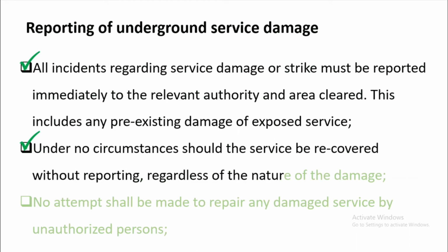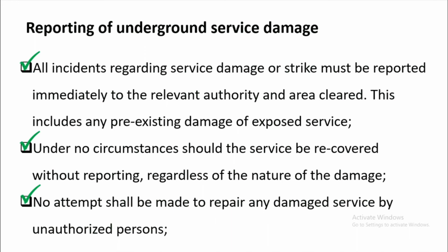Under no circumstances should the service be recovered without reporting, regardless of the nature of the damage. So don't do a recovery without reporting. Only the utility companies are authorized to conduct recovery or repair on their utility, or their accredited contractors to do the repairs for you, but it is always charged to the contractor. No attempt shall be made to repair any damaged services by an unauthorized person.